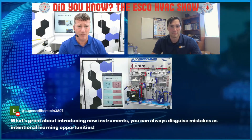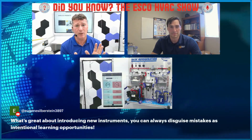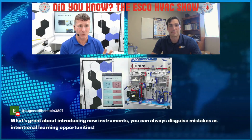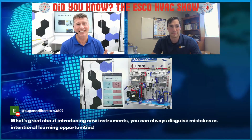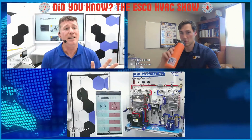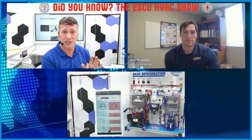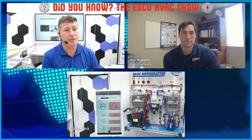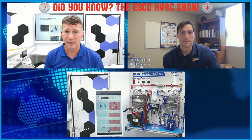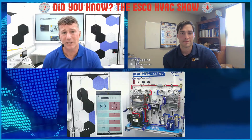It seemed to flow very comfortably, especially if I'm using equipment like my refrigeration trainer. I'm very comfortable with all of my mechanical gauges. No big deal. We know where the digitals are supposed to go. Just put them there in the same location, and now you're going to be getting that same data. And so it's more about breaking through that uncomfortable barrier of change. We know how our mechanical gauges would connect. Well, we're doing the same thing with digital. We're now just using that data to be able to get more use out of the data that we previously collected, and reducing the amount of refrigerant that we're leaking to the atmosphere every time we connect those gauges.